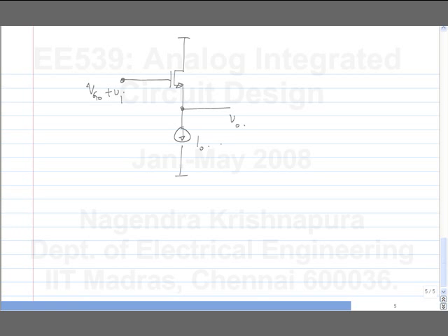In fact, let me just call this some large signal input Vi and Vo. So this is the source follower or the common drain amplifier. Again, a very common arrangement that you would have seen earlier. And in discrete cases with a large voltage across this, you can substitute a resistor for the current source, and it works more or less well. But on an IC, you almost always use a current source.